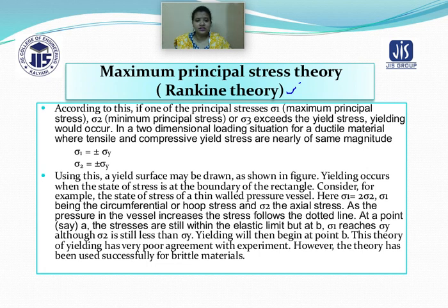So various materials have various theories of failure. If I talk about brittle material, then the most important thing is that the maximum principal stress theory is very vital for this type of failure that occurs for brittle material. By the maximum principal stress theory, a designer can calculate at what point the breaking or failure can occur. Then it is comfortable for them to design the particular product.